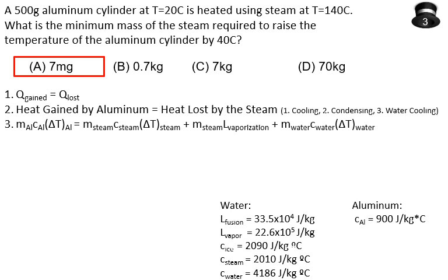So we have our equation, right? The aluminum is not changing phases ever. It's just a solid the whole time through. So its energy gained is just m c delta T, where you're talking about mass of aluminum, specific heat capacity of aluminum, and change in temperature of the aluminum. The steam, on the other hand, you have the energy lost by the steam when it's just cooling, plus the energy that is released by going from the steam to the water, and then the water itself will cool.